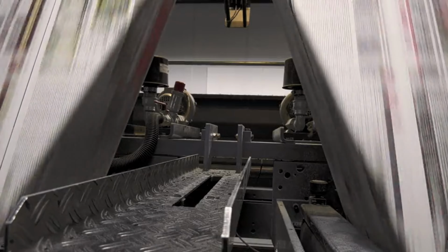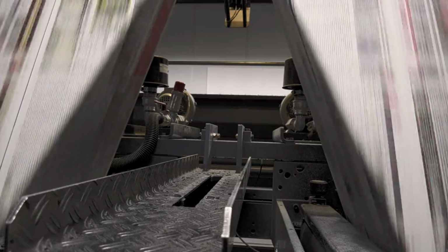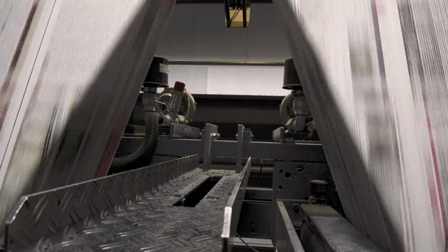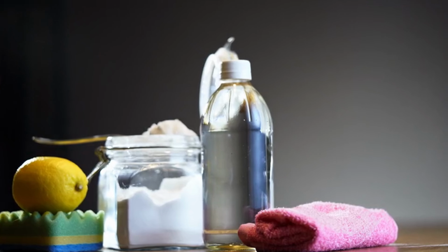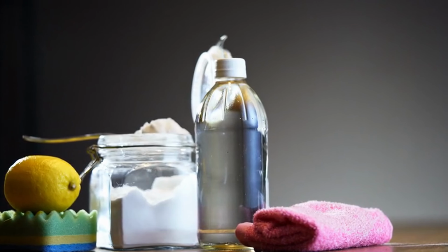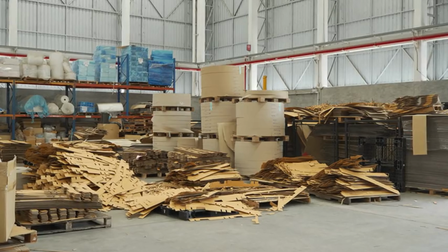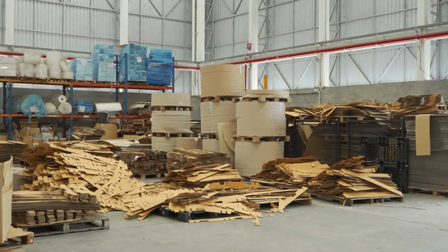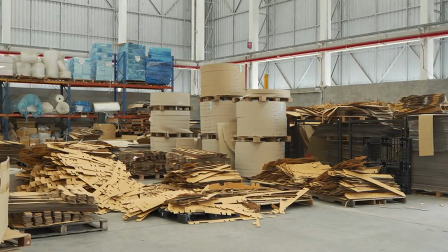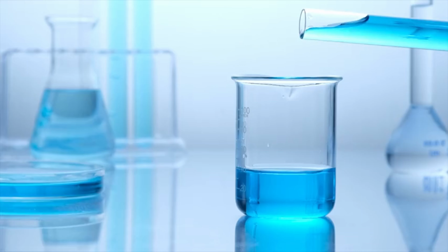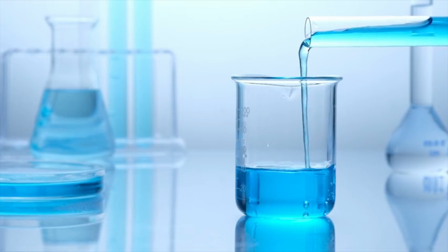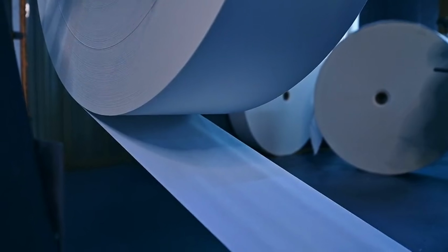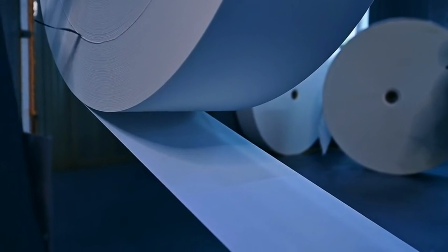A. Mechanical pulping, used for newsprint and magazines, involves grinding wood logs or chips against a rotating stone or disc refiner. Uses little to no chemicals, making it less expensive. Produces high-yield pulp. About 90 to 95% of wood is used, but paper has lower strength and yellows over time. B. Chemical pulping, used for high-quality paper. Uses chemicals to dissolve lignin and free the cellulose fibers. Produces stronger and more durable paper with better aging resistance.